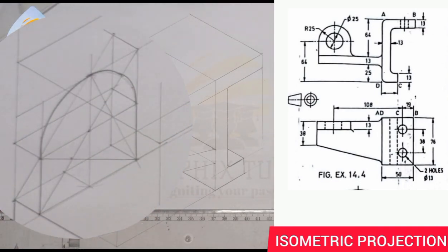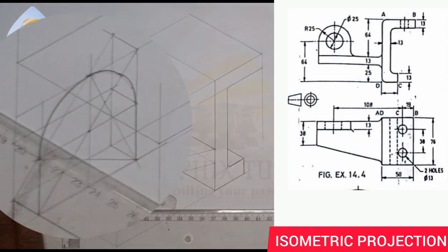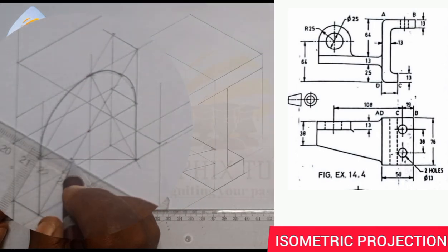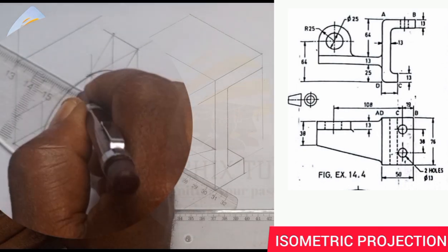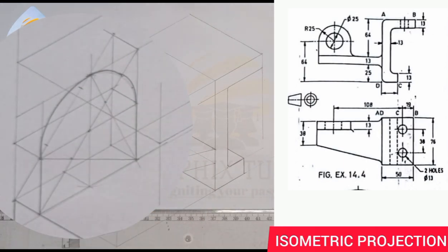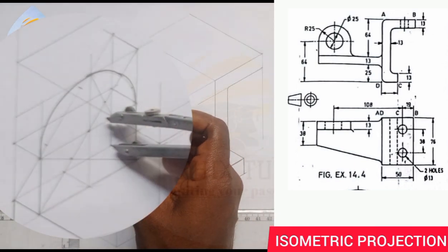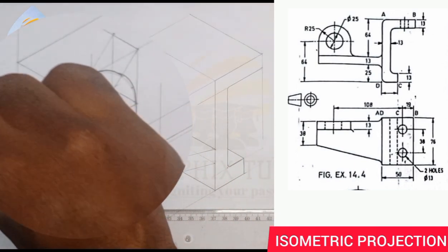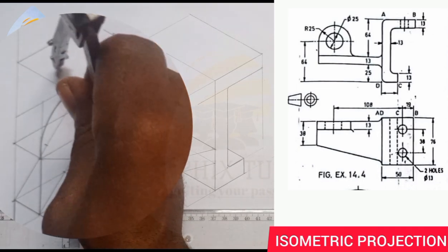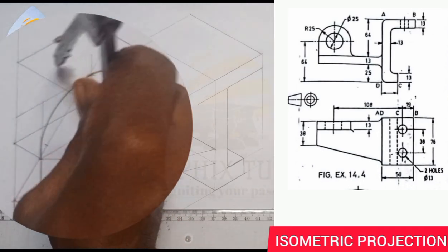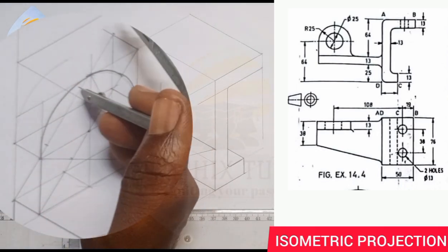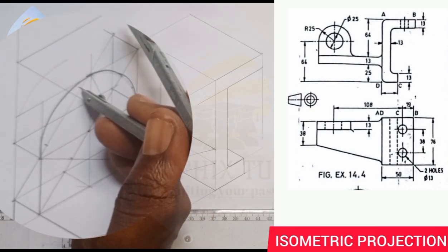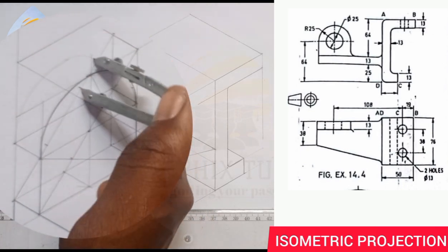Now you transfer the point. So if I place my t-square, my set square this way, this point I will transfer it to this line, the inclined line I drew. This point I'll transfer it to this line also, the inclined line I did. So now I can easily combine both of them. So what I will do, I'll place it here. I'll take it to this point and I'll draw this way. Can you see that? Then I'll place it at this point here because I use this to get this arc. So I'll use this to get the other arc here. I'll just stop here.